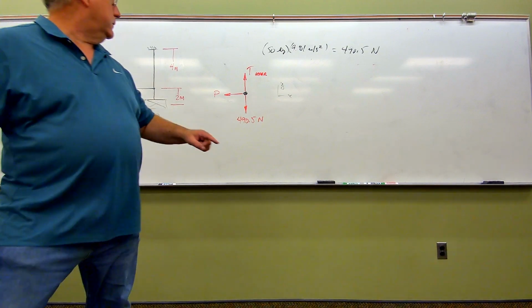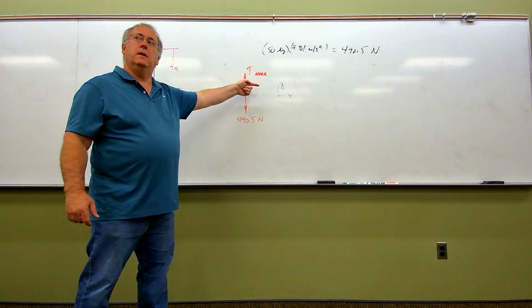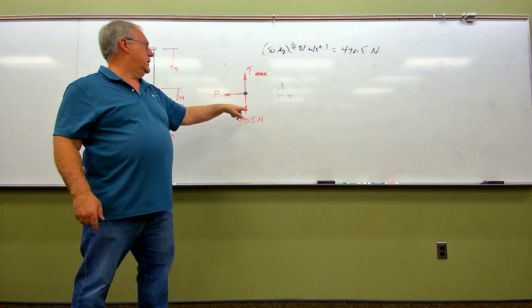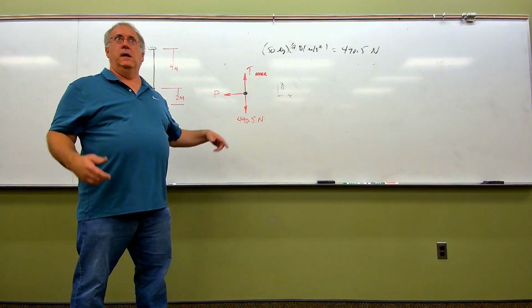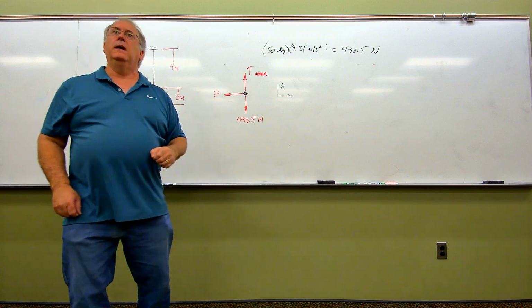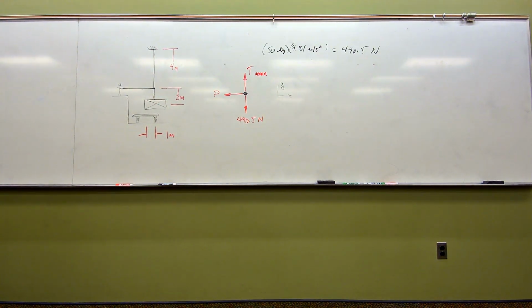But we're just summing forces in the x direction, right? P is a purely y directional force, so nothing there. Summing forces in the x direction, you just think of the equation. I'd have minus P, to your point, equals what? Zero, exactly. So using this free body diagram right here claims that the worker wouldn't need to apply any force to the rope. The crate's going to magically work its way over to above the trailer.